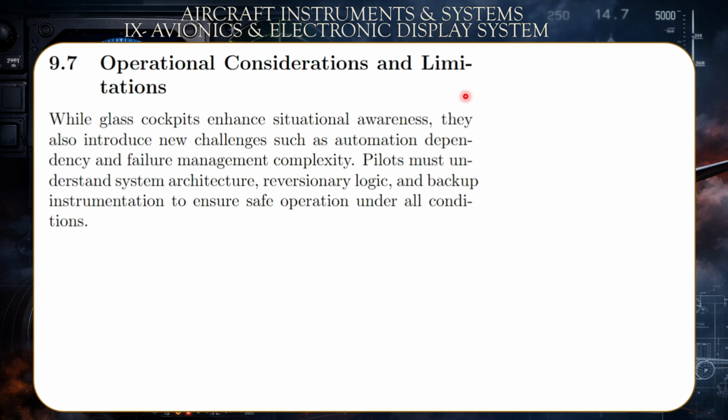Operational considerations and limitations. While glass cockpits enhance situational awareness, they also introduce new challenges, such as automation dependency and failure management complexity. Okay, so it's much more complex to troubleshoot in such a case. Pilots must understand system architecture, reversionary logic, and backup instrumentation to ensure safe operation under all conditions.